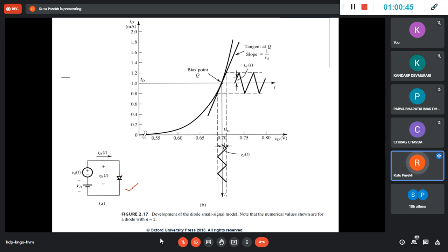I have to turn on this diode, and to turn it on, you give 0.7 volt. So you will need a battery to turn it on, and you will set it. If you set it to 0.1 or 0.2, then it is still dead. So you will make it 0.7, the diode is on, and now to that circuit, you will give the voltage of the signal that you want to process.